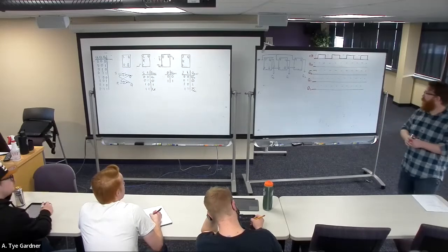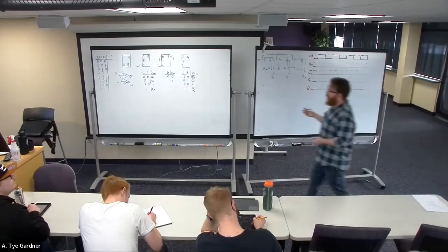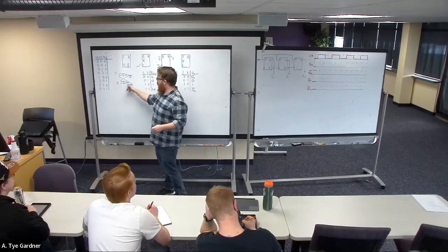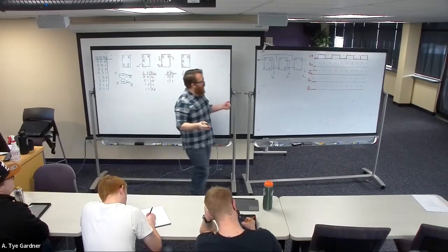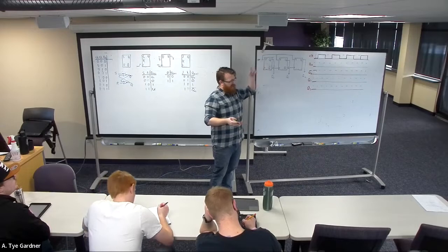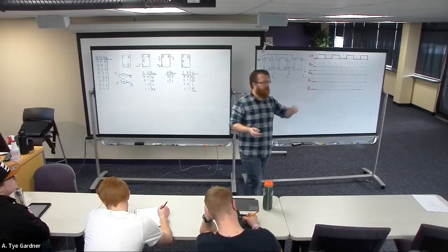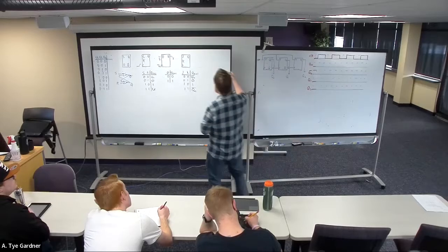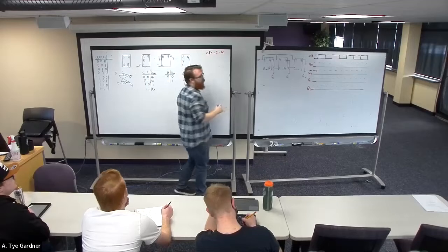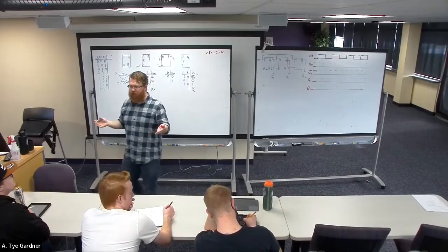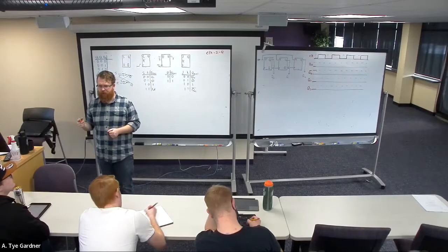And so now we have to remember that devices aren't ideal, right? They're made out of gates. And in fact, it's made out of several layers of these gates with associated logic. So it's not unreasonable to think that these T flip-flops travel through like 8 gates before they get there if you've optimized it. So it's got a lot of delay, right? We call that delay clock to Q, meaning how long after the edge of the clock it takes for Q to change to whatever it needs to be.